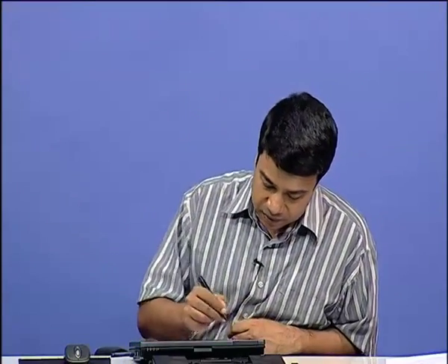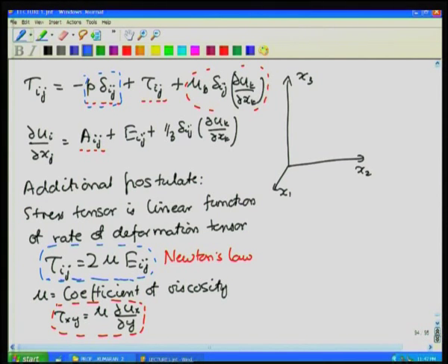of coordinate systems. Okay. Basically, the difference between the Newton's law that I have written for you in tensor form here, okay, and the one that you would simply write for a simple one dimensional flow. Okay. So, the way I have written the Newton's law in tensor form, it is frame invariant, okay. And similarly, it has to be frame invariant no matter how one formulates an equation for a non-Newtonian fluid.